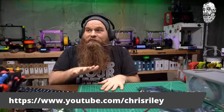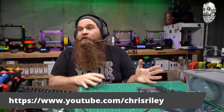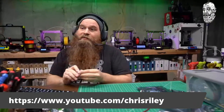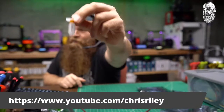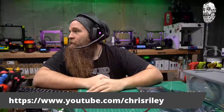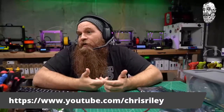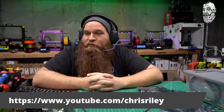But remember, your very first step is figuring out what your components are. Are we adding a probe? Because if you add a probe, this changes some things. What else can we add? If you have mechanical end stops, sensorless homing, these are all features that we're going to mess with.